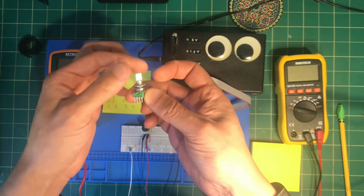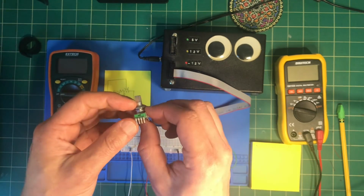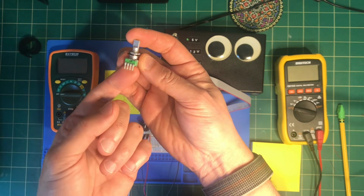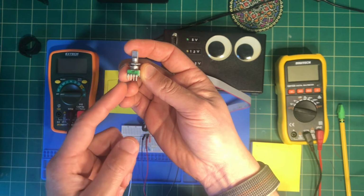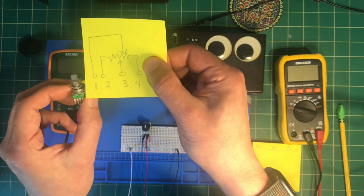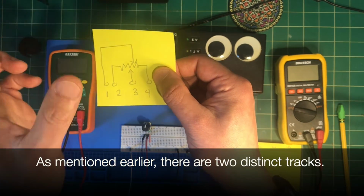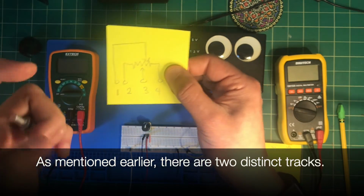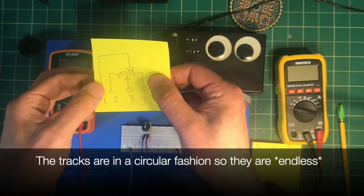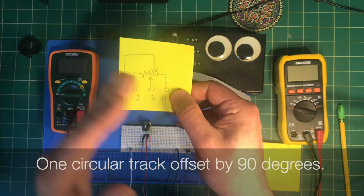First off, this is the endless rotary potentiometer that we've been looking at. One thing you might notice that is different from most other potentiometers is that this has 4 pins instead of 3. Here's a little schematic of how this is wired internally. Now, I don't know if there is just one track and then the wipers are offset, or if there are 2 separate tracks. That's unclear from the data sheet. But what I do know per the data sheet is that the values are offset by 90 degrees.